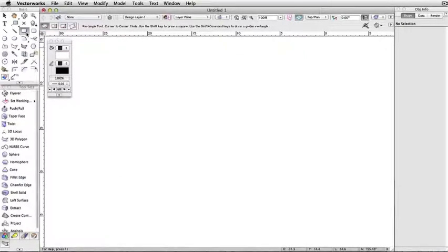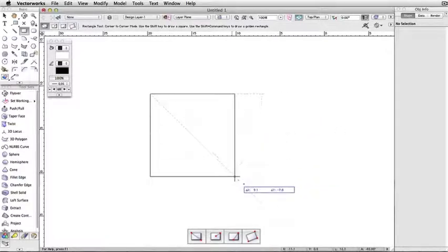The rectangle tool, used for creating, as you may have guessed, rectangles, can be accessed by pressing 4 on the number bar along the top of your keyboard. This tool has 4 modes, the first of which is corner-to-corner mode.